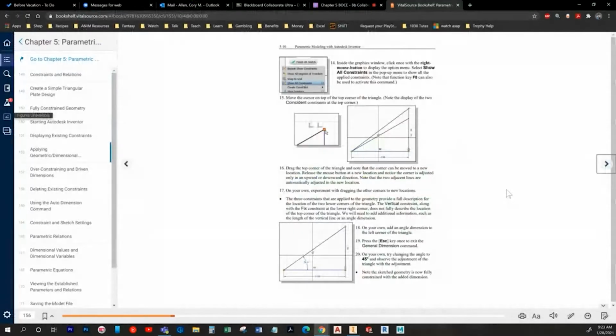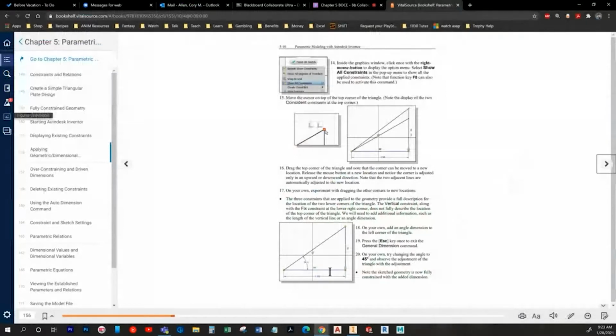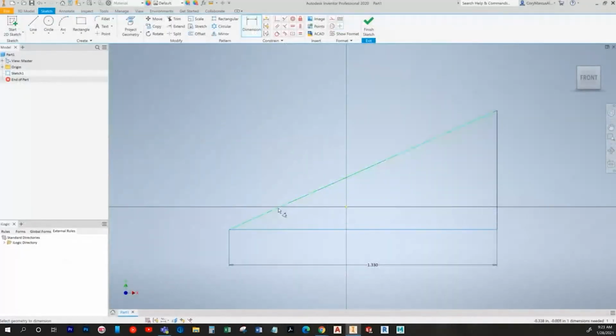All right, so then it's kind of showing that when you see these lines, and I've talked about this in the other video, when you see they're blue, that means there's something left that needs to be messed with. Now, if you grab the line and pull, you're probably not going to get it to move, but if you grab the endpoints, you can see it's flailing. So this immediately tells you, you need either a height here or an angle or something of that sort, because this end doesn't move. So you're basically just missing that one value. In this case, it chose to do an angle. So I'm going to just click. I think that it's just putting whatever's there.